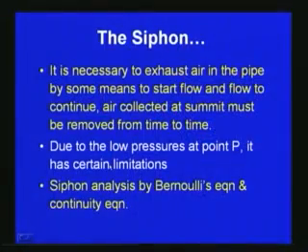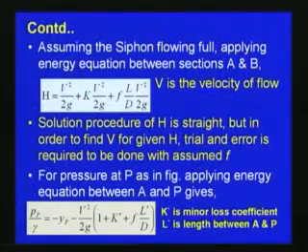So, the siphon analysis we can do through Bernoulli's equation and the continuity equation, a simple analysis. Here we have to find out either the pressure at the elevated location, or how much liquid has to be transferred, or the head loss in the process. So, the different kinds of problems which we discussed with respect to pipe flow systems are applicable here also.